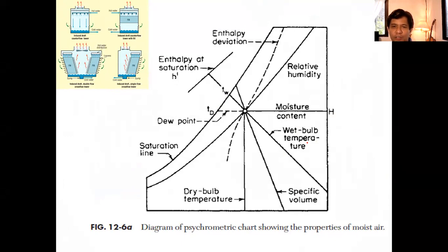No? In order to solve that problem, pag merong wet bulb na given. So, paano ba ginagamit ang psychrometric chart? Madali lang naman. Just locate the wet bulb temperature in this curve. Itong sa curve na to, nandito yung wet bulb. Just locate this. Kung gusto niyo naman, dito niyo rin i-locate. Tapos, actually, kung ano yung katapat niyan dun sa taas, yan din yun. Just draw a line. Halimbawa, dito nakalagay 50. Pag nag-draw kayo ng vertical line from here, dire-diretso, nakalagay din dito 50.